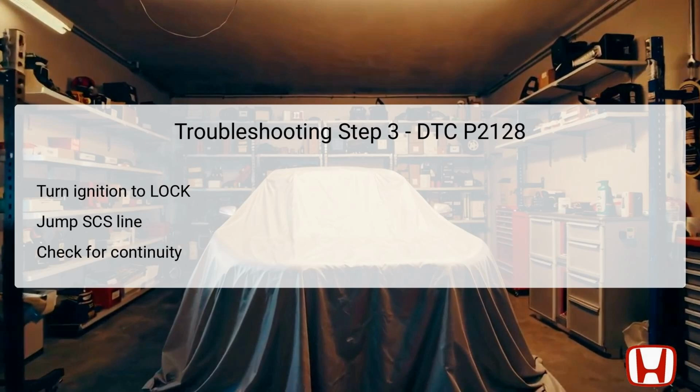Test point 1 is the LT blue wire at the ECM connector A, 49P, terminal number 45, while test point 2 is the body ground. A positive continuity check indicates the SG5 wire is functioning correctly, necessitating further actions like updating the ECM if the software is out of date. A negative result signals an open in the SG5 wire that must be repaired before moving forward.